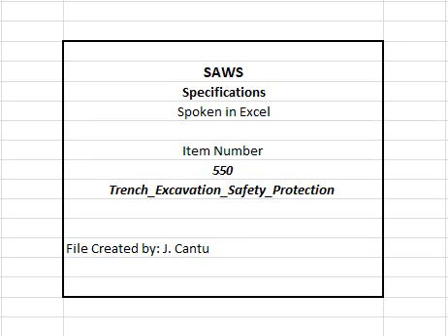1. Payment shall include all components of the trench excavation safety protection system, which can include, but not be limited to, sloping, sheeting, trench boxes or trench shields, sheet piling, cribbing, bracing, shoring, dewatering, or temporary diversion and proper recapture and transportation of water to provide adequate drainage.